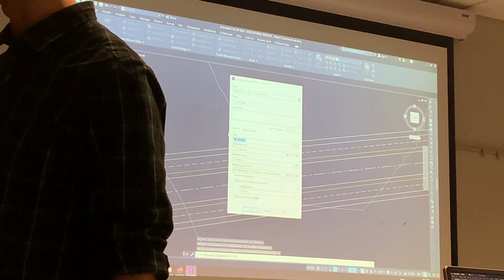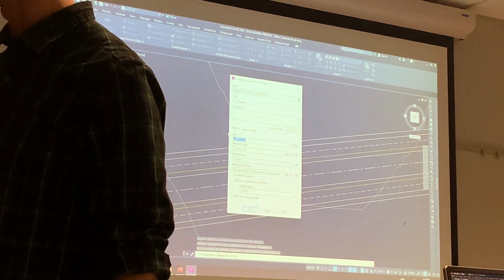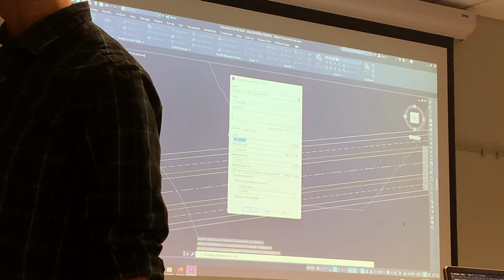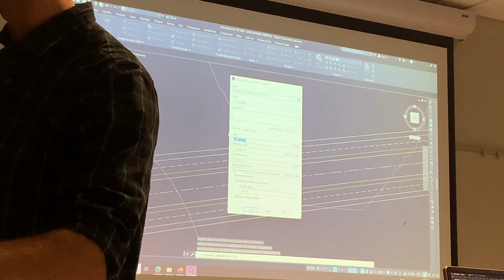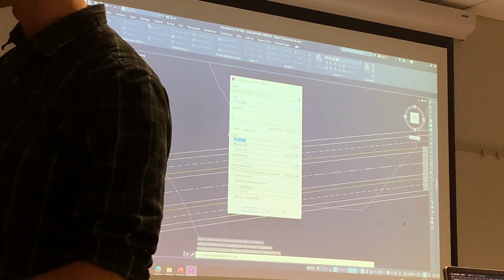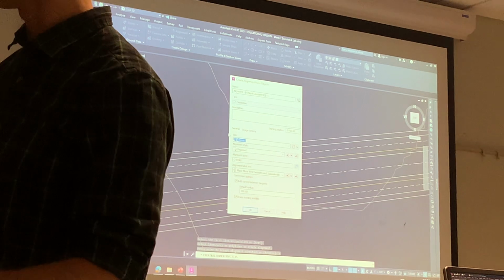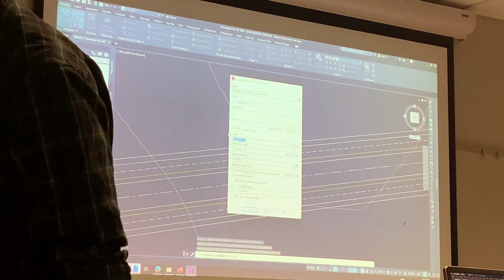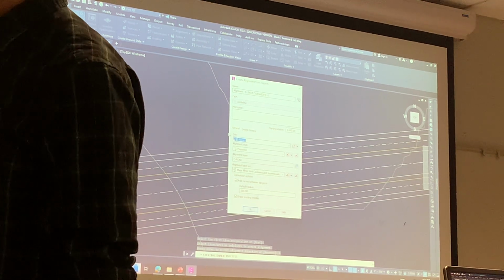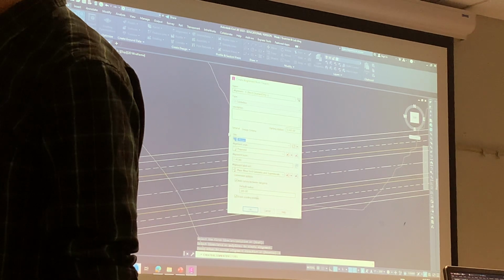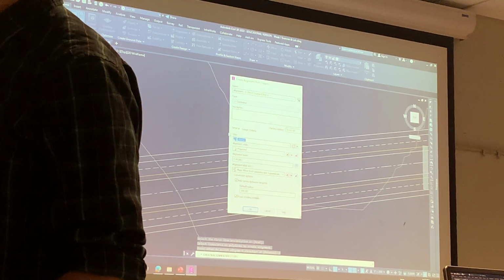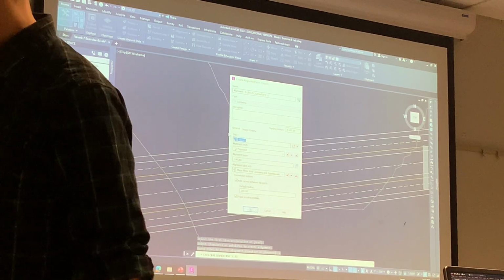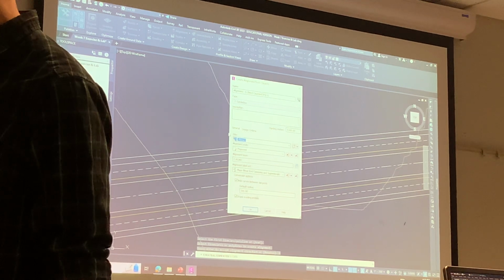Oh, you know why? Well, here, escape. Because you guys did it in quarter. So zoom in a little bit so you can know that you're selecting it. Alignment from objects, select the center line, and before you confirm, zoom out. There you go. Now that you're zoomed out, now you can. Okay, so now it's fine. Quick escape. So you gotta join those two together. There you go.